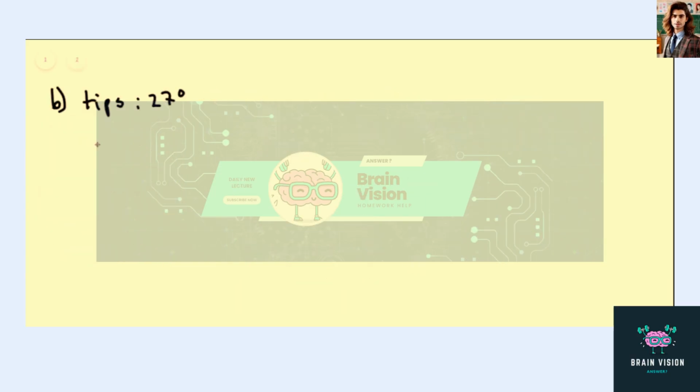And then you don't have to redo the calculation. We know that our beta is equal to the arctangent of the coefficient of friction, which is 0.4, and that is 22 degrees.